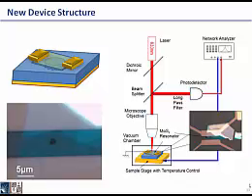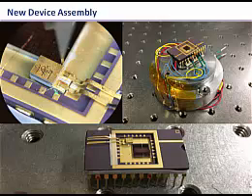So here shows an example of the device, a monolayer MoS2 flake suspended over a 2-micron micro trench. And certainly, the measurement setup needs to change because now the device is wire bonded. I have to move the temperature sensor close to it. So I also wire bond the temperature sensor on the same die pad as the device and mount the entire package onto the cooling stage, which we saw in the slides before.